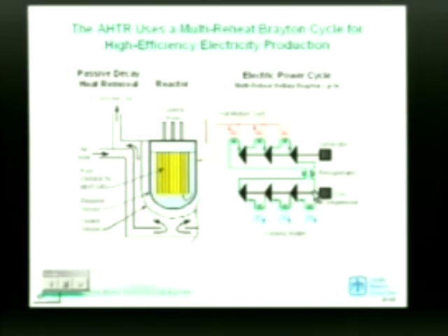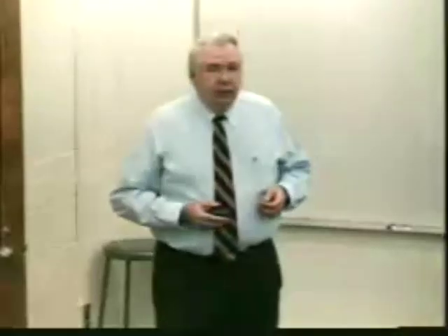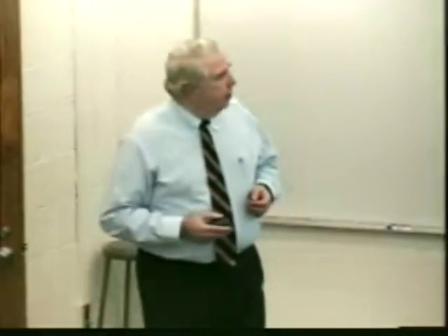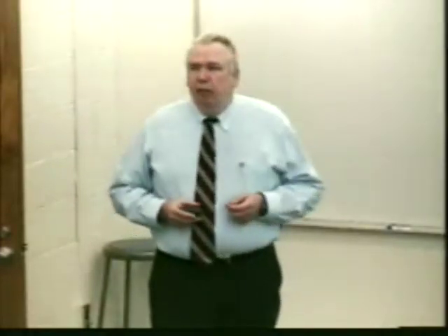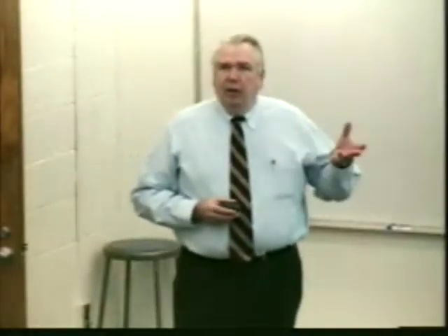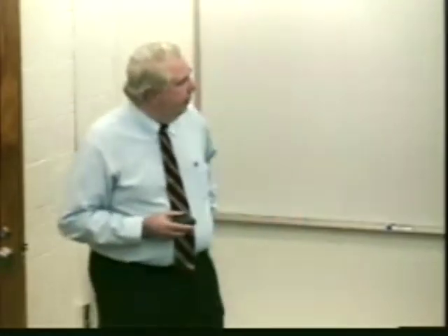The helium is then, of course, cooled, goes through recompression, solid-state recompression, and back to this multi-reheat cycle. Now, the ability to deliver the heat at a high temperature and use it has some powerful implications in terms of thermodynamic efficiency. That is, how much energy we convert to electricity.